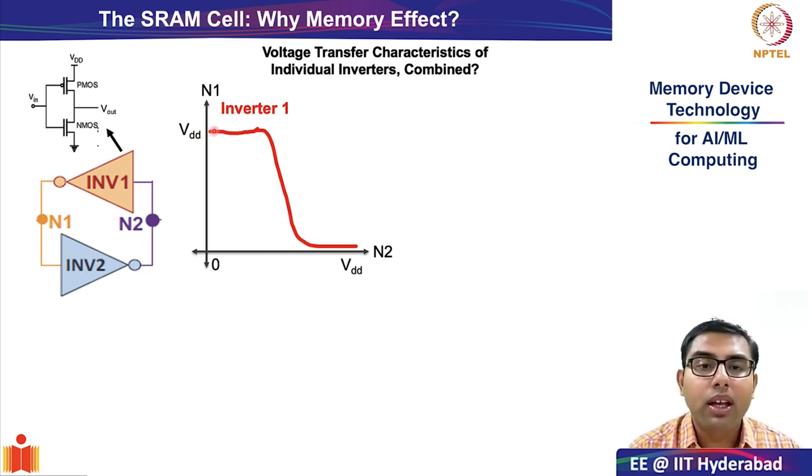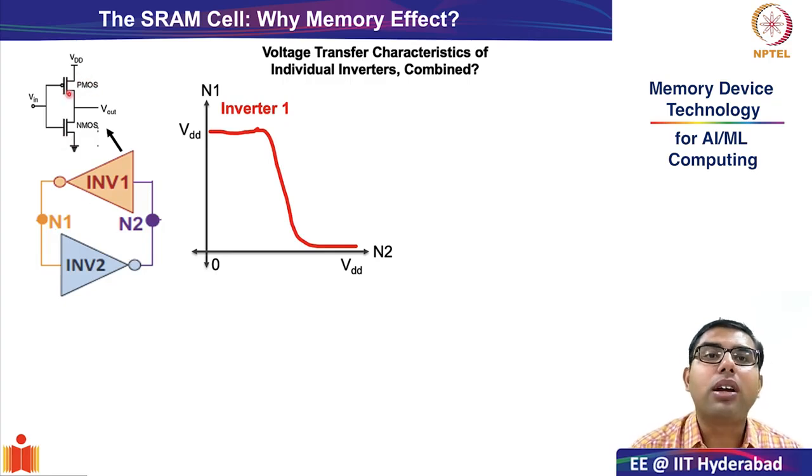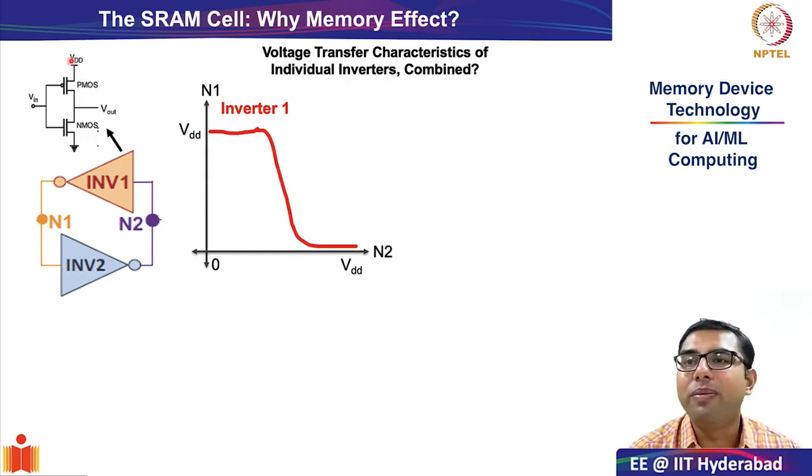Why is this happening? This is fundamental in CMOS design, but it might be worthwhile to do a very quick recap. This is because of the very simple structure of the CMOS inverter. Just imagine if the input Vin is 0, the NMOS will be turned off, the PMOS will be turned on, and therefore there will be a direct path between VDD and Vout. That's why the PMOS is also called a pull-up transistor, because when it is active, the output is pulled to VDD.